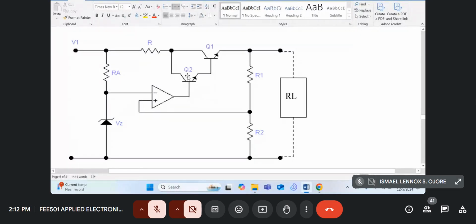So if the gain of that transistor is, say, 50, then at its emitter, we'll get approximately 50 times 10, which is half an amp or 500 milliamps. And then that half an amp will be amplified again by this Q1.